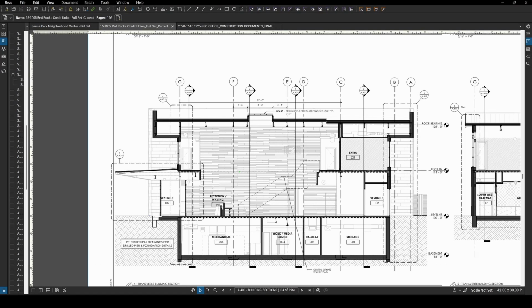One thing you'll notice in this building section is that instead of having construction shown, I mean, we are showing the corrugated metal deck in section here, but we've decided to blacken all of these. There's a thought process that when you have black building sections, it kind of indicates a schematic section. But in this set of final construction drawings, we actually did produce final drawings with blackened section cuts.